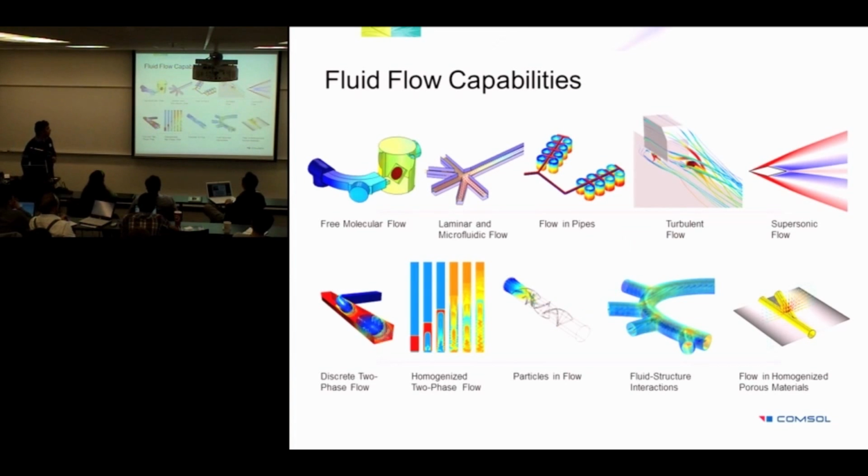For the fluid flow capabilities, it can range from free molecular flow to anything like supersonic flows, but that's what we will be doing in microfluidics. We'll be confining more on the laminar part or the creeping flow. Or we could go into the free molecular region where the size of the device goes very small so that the molecules basically hit the walls instead of hitting each other. So you basically then solve for free molecular flow, more in the statistical region rather than assuming continuum in your modeling.